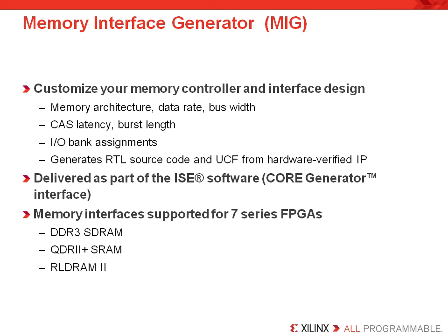If you want to build your own controller, there is also documentation about the physical interface. But as you will see, the MIG will require you to know the device, choose the type of controller, choose the interface, any DDR3 options you would like to select, the input clock options, and also then to go about defining where you would like your pin locations. Now, pin allocation is simple with the utility, and it assigns byte lanes to an I/O bank.